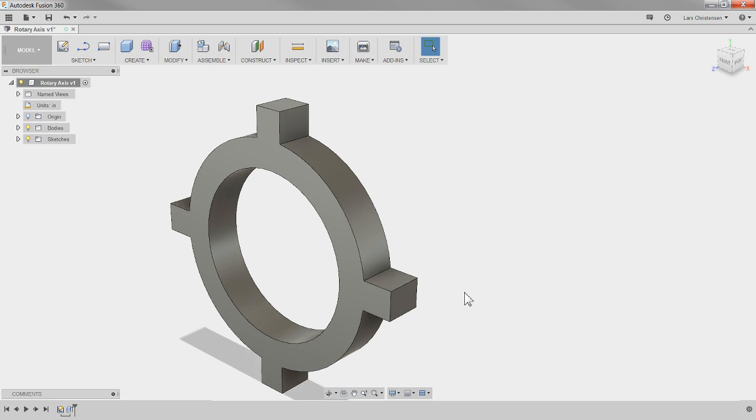Now, let's talk a little bit about fourth axis. So you can do fourth axis inside of Fusion. You can do it different ways, right? So there is what we will call mill turn, what also could be called live tooling. And then there is also, if you put something like an A-axis on your vertical machine, for example. And then, of course, if you have a horizontal machine, your tombstone might be spinning around, and that could be your fourth axis also.